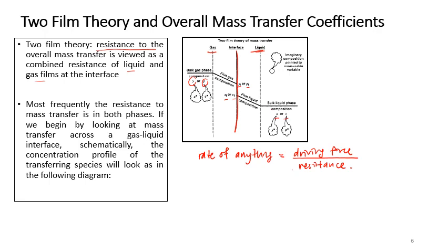So in mass transfer for absorption, the driving force is the difference in concentration, and the resistance is the resistance in the liquid and gas films at the interface.